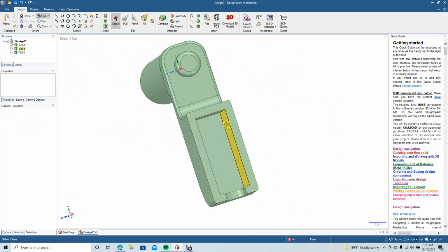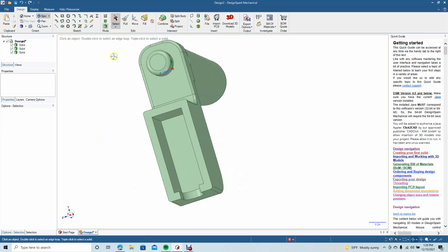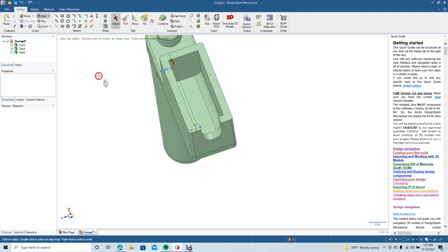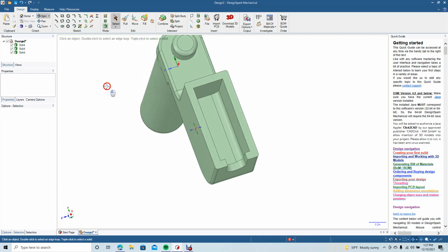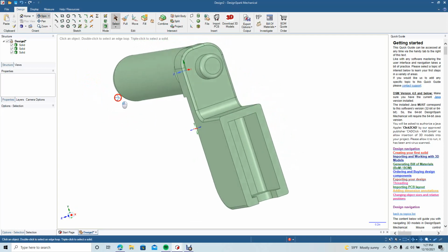I want to fillet the inside lines here, so there's a radius for the tuning peg of the guitar. So we'll click, put a pretty extreme one in there, 0.09. And now we're going to spin this one. Go ahead and pull. Do the same on this side. 0.09. That's just a little contour place for the key, the tuning key, to sit. Okay, that looks pretty good.